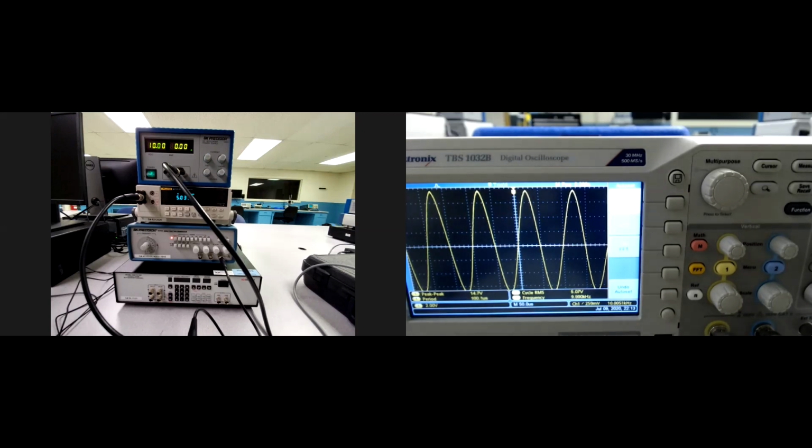Okay, so I'm going to read out loud the description for assignment 3. It says, in assignment 2, the digital multimeter was used to quantify the amplitude of an AC signal. In order to quantify a DC signal, the multimeter AC-DC switch must be set to DC. The oscilloscope is capable of measuring 2 simultaneous signals.